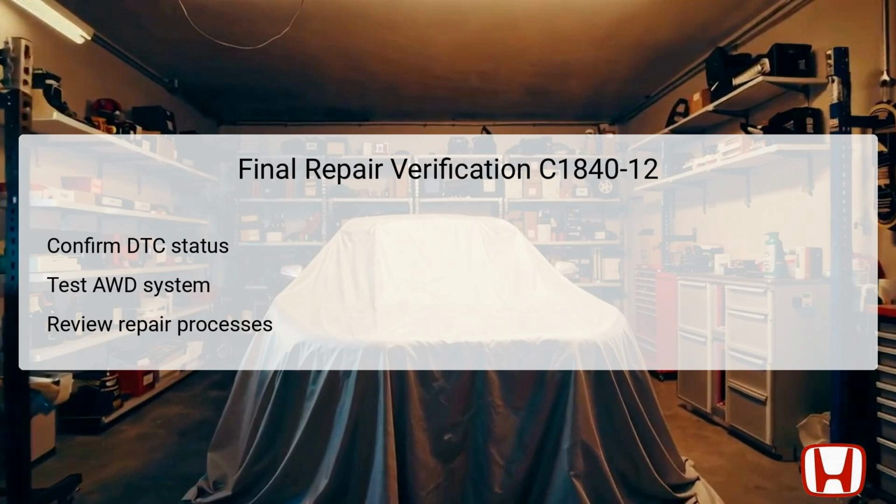After completing all necessary troubleshooting and repairs regarding DTC C1840-12, it's crucial to conduct a final verification of the repair processes undertaken. Start by checking the status of the DTC to ensure it has been cleared from the system and does not reappear. Following this verification, test the operation of the all-wheel drive AWD system to confirm that all functions restore normality and the system performs correctly across a range of conditions.